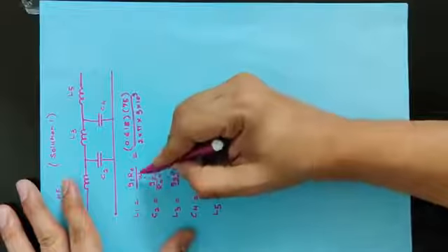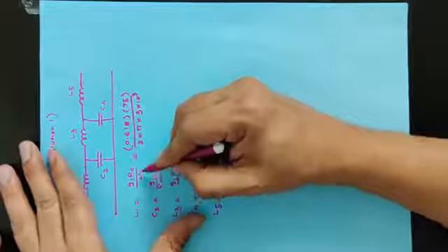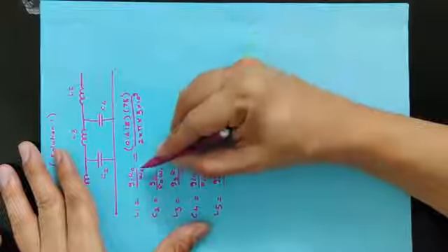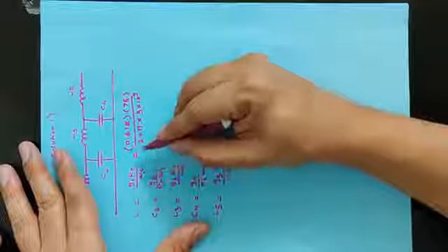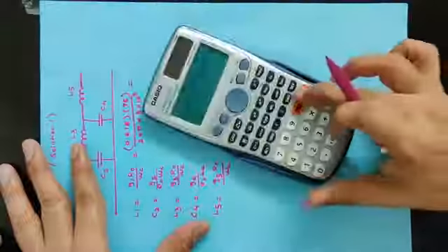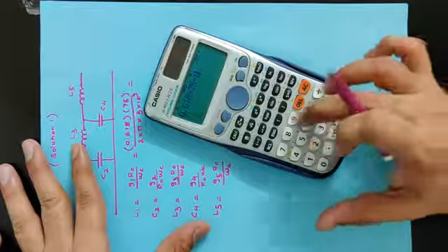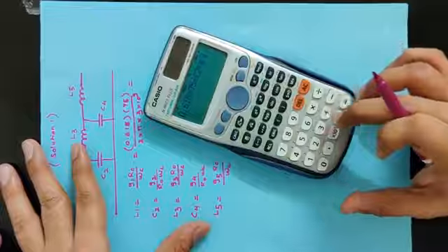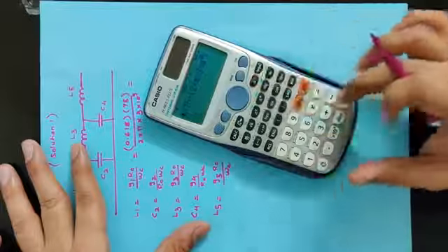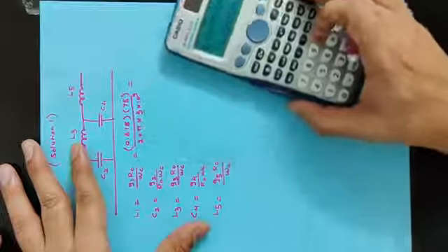Students most of the time make a mistake over here. They substitute fc over here, but this is omega c. So it has to be converted in terms of fc: omega c will be 2 pi fc. So we'll calculate this: 0.618 into 75 divided by 2 into pi into 3 into 10 to the power 9. So it turns out to be 2.459 nanohenry.